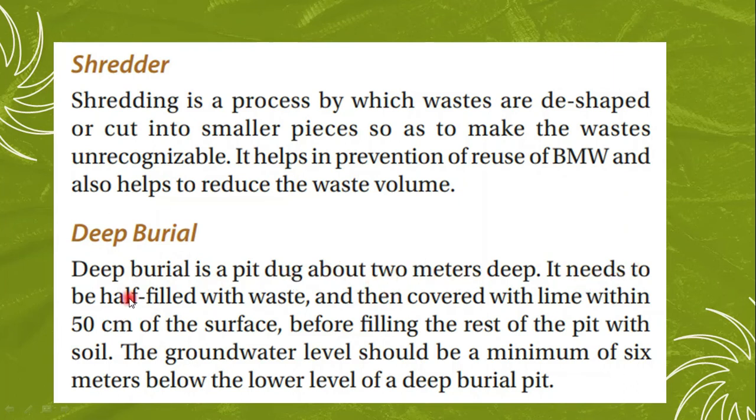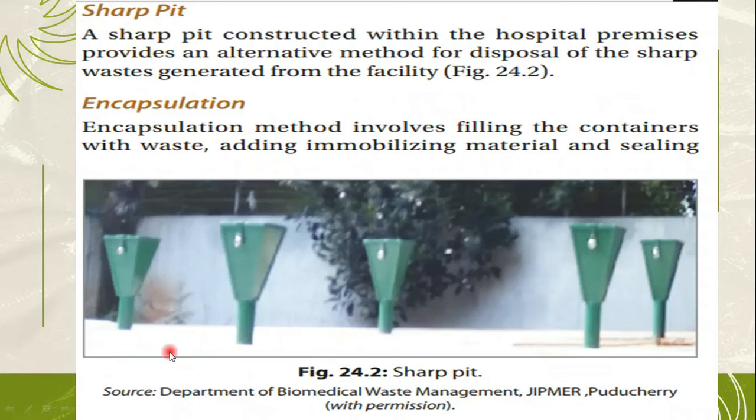It needs to be half filled with waste and then covered with lime within 50 centimeters of surface before filling the rest of the pit with soil. The groundwater level should be a minimum of 6 meters below the lower level of the deep burial pit.